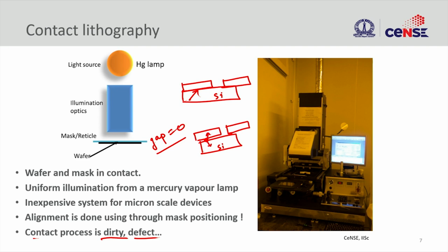So we should make sure that there is no particle between these two surfaces, so that you clean the surface properly. And just for clarity, this is silicon, you will always have some photoresist. Good. So the technique is pretty straightforward, but you should be careful about the surface contamination and how you are going to handle it if there is any contamination.